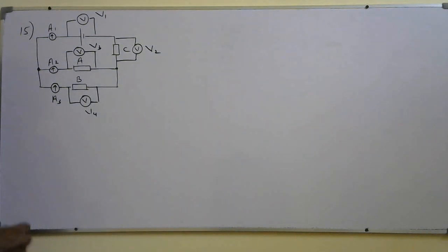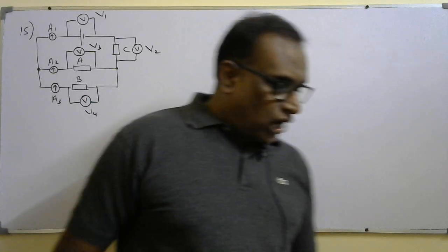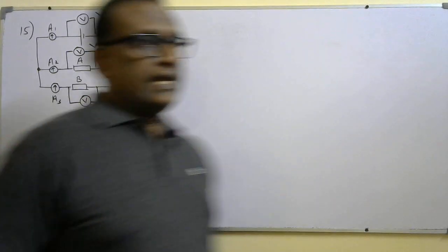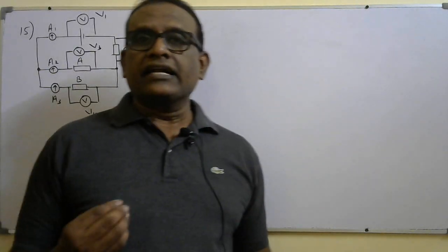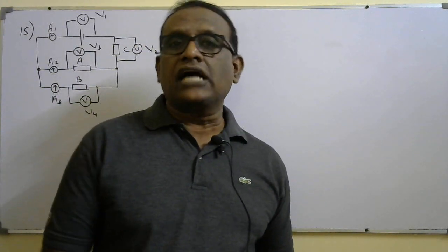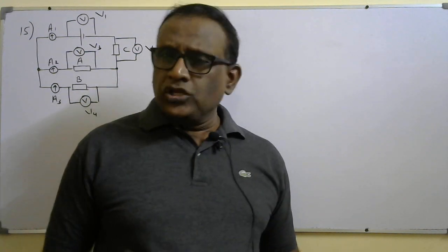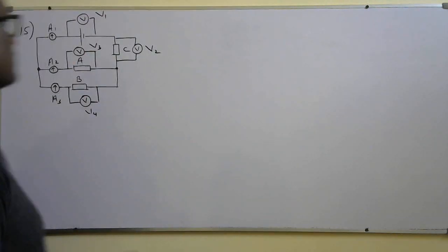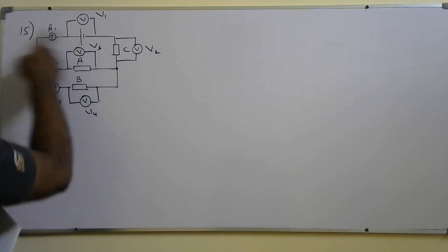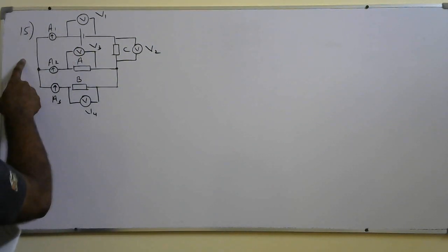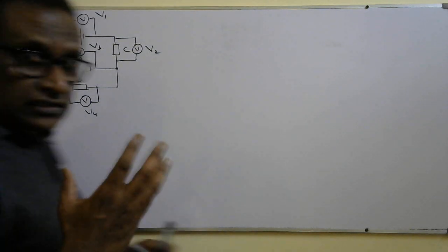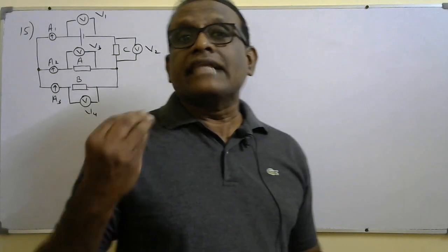Okay, so we can explain how the energy and charge behave. First, current flow. You should say current is the rate of flow of charge, that means the amount of charge flown per second. You know Kirchhoff's first law. It says the current from the cell, if I call it I1, will be equal to I2 plus I3. You can find that by using the ammeter readings.